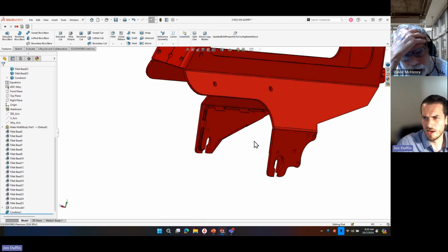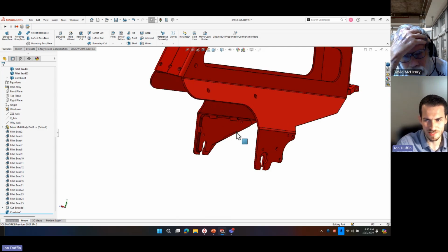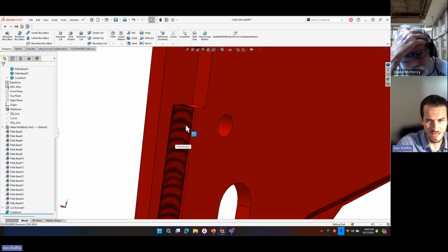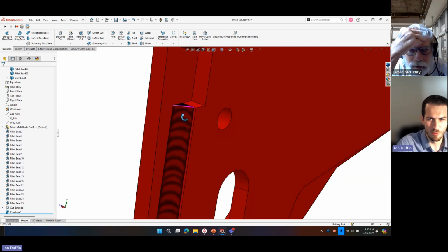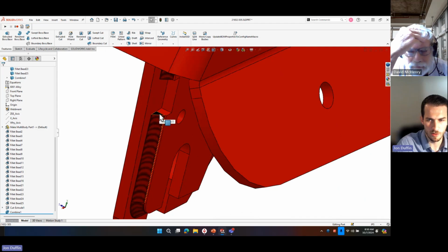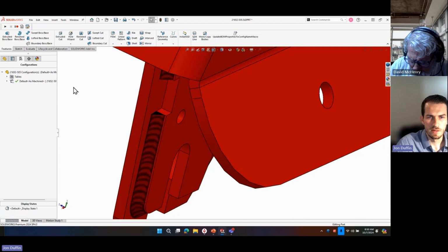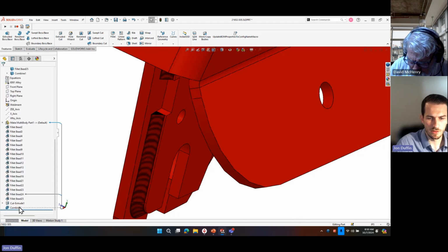Now, you're absolutely right. It's evaluating how many bodies, what detail do you need for the analysis, especially within SimulationXpress, where we aren't doing mesh control and things there. Getting down into the detailed stress of the welds, probably not important, because we are just getting those ballpark results to begin with. But let's take a look.